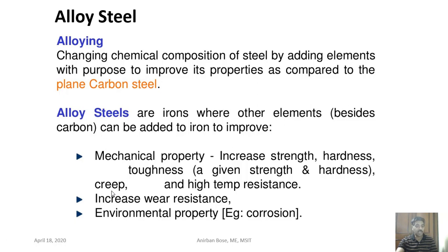If the temperature is very high, what happens is that with the increase of time we observe that deformation takes place. You are not increasing the stress on a mechanical component, but with time you find that the deformation is continuously increasing, and this particular phenomenon is called creep. But creep happens generally at a very high temperature, like in turbine blades, gas turbine blades. So creep is a thermomechanical process, a time dependent deformation that occurs.